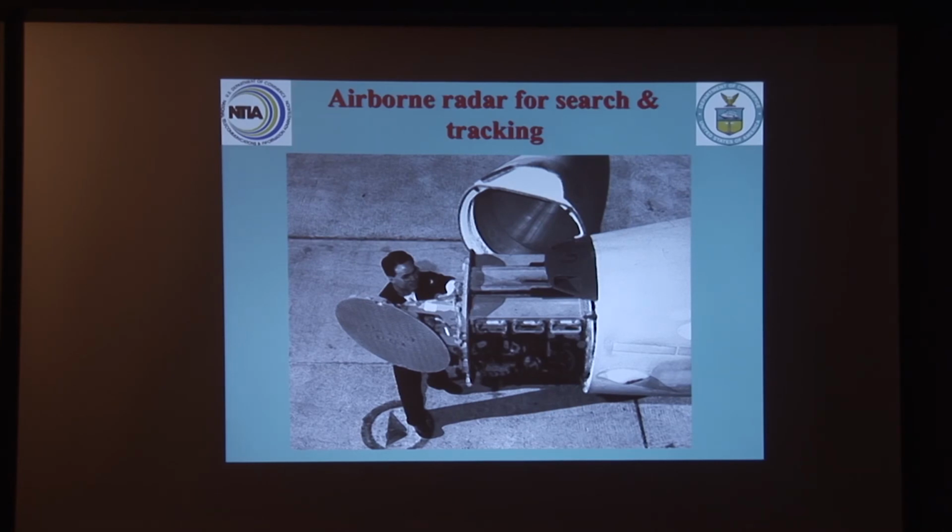They're used for search and tracking a lot. Here's the antenna that would be sector scanning like this in the nose while the airplane's flying. Here's the rest of the radar unit built in back here. Obviously, space and weight are at a premium. Therefore, solid state is not a favorite for these. Tubes are smaller and lighter weight and higher performance.